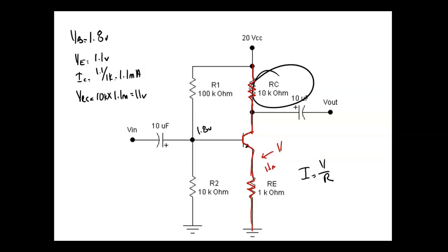So I'll show y'all some actual circuits where we see R1 like this. Schematics show you the logical operation of the circuit. They do not show you how the circuit is actually constructed on a circuit board, right? And we see that in this class where you try to do the circuit exactly the way it's drawn. So you try to measure VB, you try to get the base of the transistor. When you can measure it, you can measure it on this lead or that lead, right? Which is a lot easier. So that's what I'm going to do when I measure these.